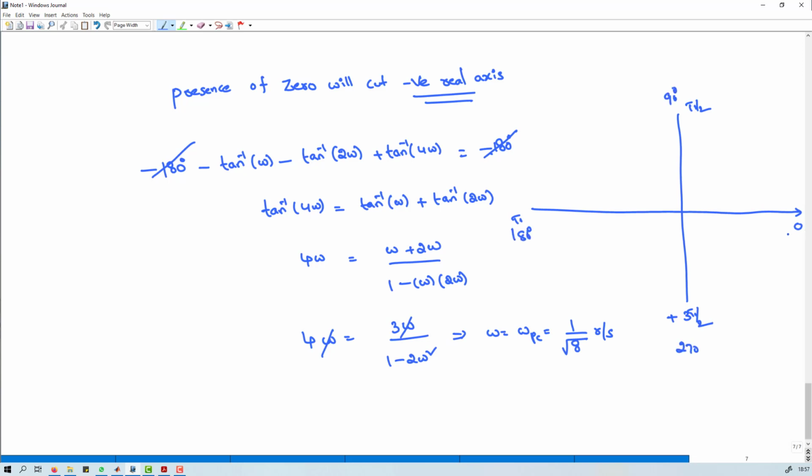Obviously it has to go in the third quadrant, cutting towards the second quadrant if you take normal quadrant variations. So having those magnitude and the phase, let us draw that, and easily you can go like this. Yes, now it is very simple. Now you can even easily find out what is the value of omega there and what is the magnitude occurring here. That can be easily found out by substituting the value of omega directly into the magnitude plot.